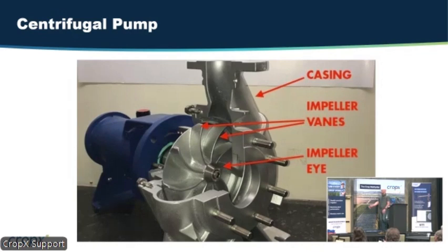Now, keep in mind that most of these pumps, unless you have VFDs, and that could be a whole 4-hour session on VFDs, but most pumps, once you turn them on, they're on, right? So that impeller's spinning at the same speed no matter what's going on. Okay? Now, depending on how much flow, you have different pressure, and that's known as a pump curve.